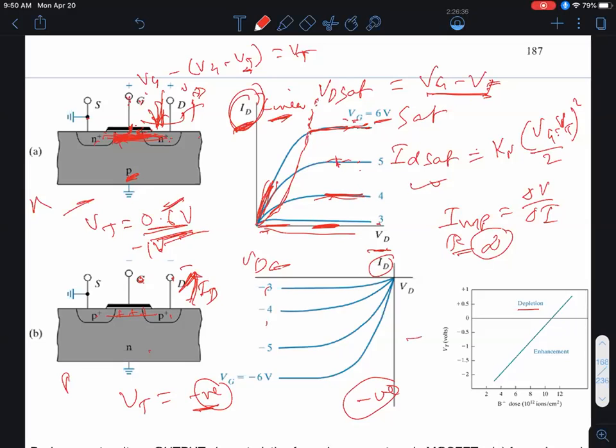All right, so that's kind of shown over here for this sort of P-channel MOSFET, okay? So if my threshold voltage is negative, those are called the enhancement mode devices. But if in the P-channel, the threshold voltage happened to be positive, the transistor would be normally on at 0 gate voltage. And then you'd have to apply a positive gate voltage to push those implanted holes away from the channel to turn the transistor off. Generally speaking, that's not desirable. Enhancement mode is typically what's used, okay? These are used rarely in niche circuit applications like resistors and things like that.